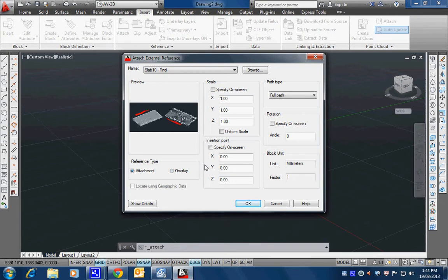Then if you do some modification, for example, add some walls, and then you decide to save this drawing and call it floor plan or something like that, and then you decide to give this floor plan to the electrical guy or girl, whoever, to do the lighting. So you give them the file. In fact, you zip it up and do the transmit thing, do the right thing, give it all to them, and so they will pick up the drawing file, open that plan up, and then they will want to draw the electrical on top of that.